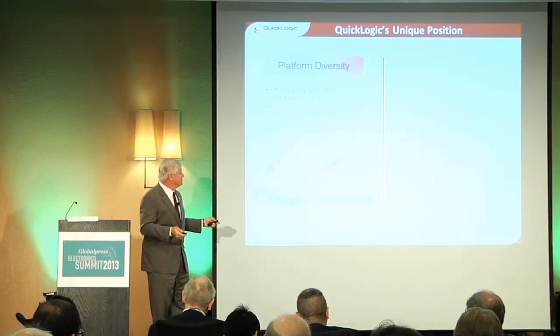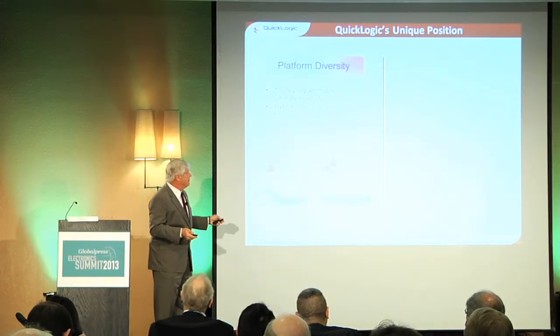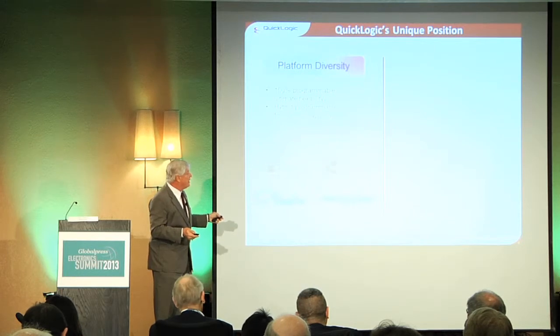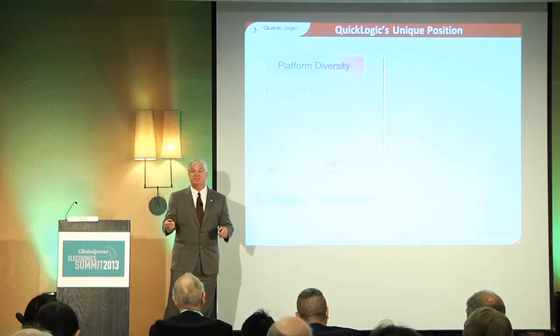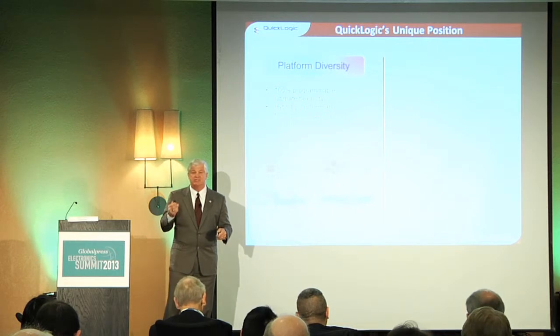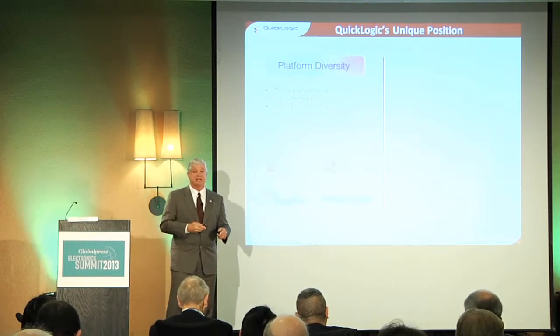And the other reason we would do it is if we have a technology that is really pervasive across the subsystem that we're trying to penetrate, like, let's say, USB, or if you have followed us, our visual enhancement engine, that makes sense to harden, because there obviously is a penalty for the flexibility of programmable logic, and that is larger size. So we have this hybrid of circuitry with programmable logic and hardwired logic around it to give the most cost-effective, low-power solution available in the mobile industry today.